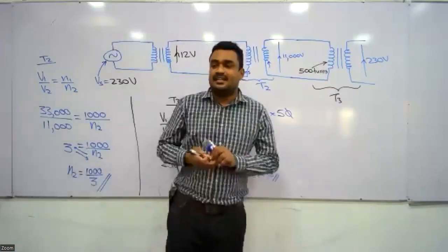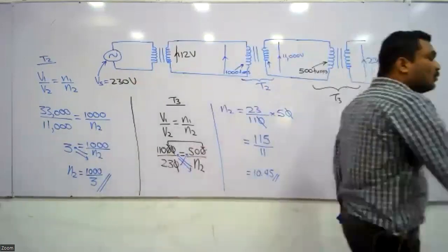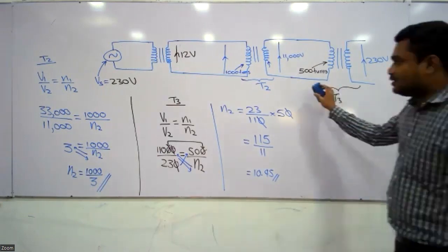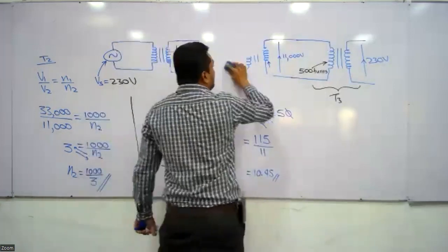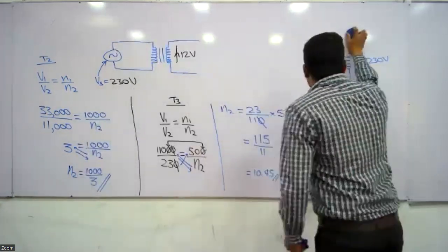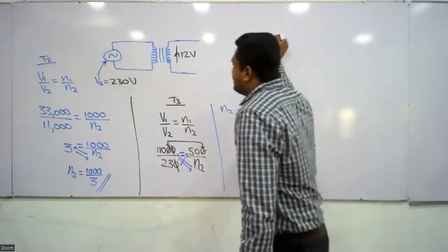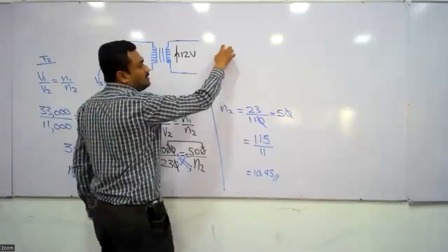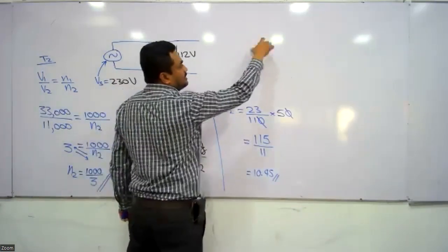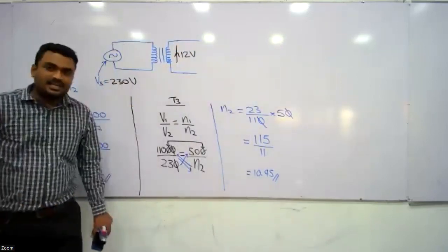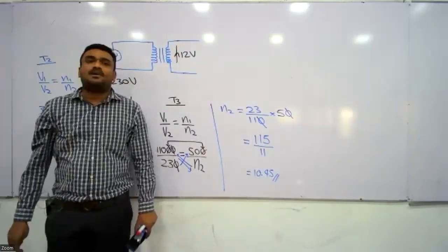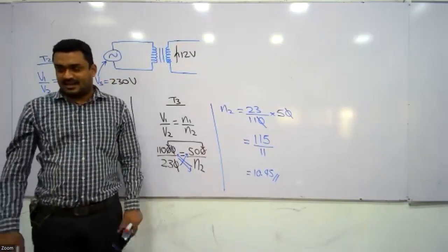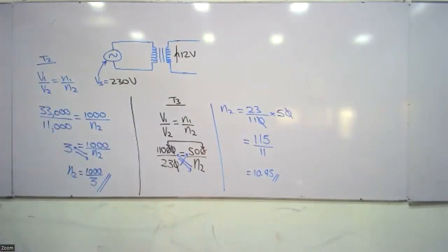This 12 volt is then converted to DC by using a full wave rectifier circuit. Such a combination, a transformer, full wave rectifier, a capacitor, safety diode, Zener diode, all of that combination is known as a power pack. In day-to-day life, we call it a power pack. Let's discuss one more example for a power pack here.